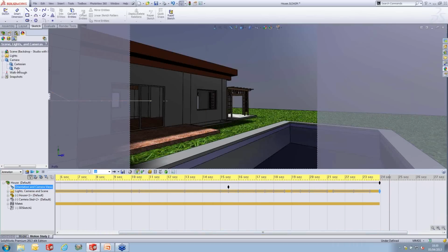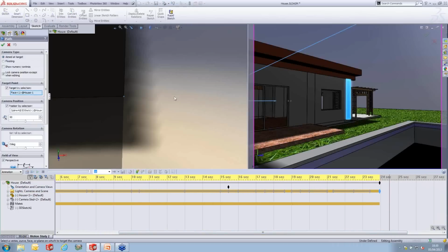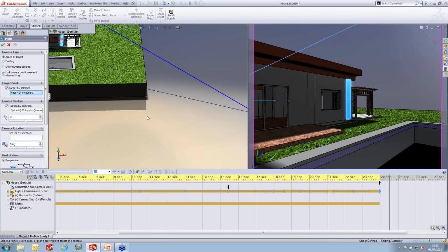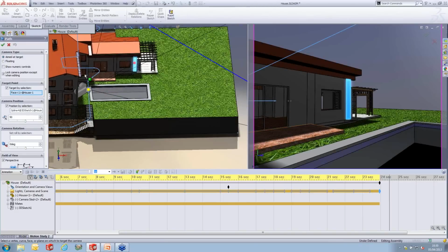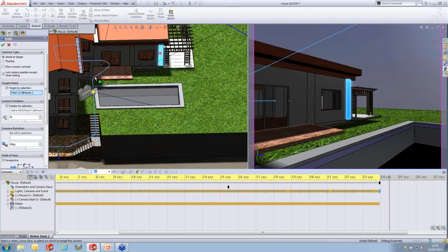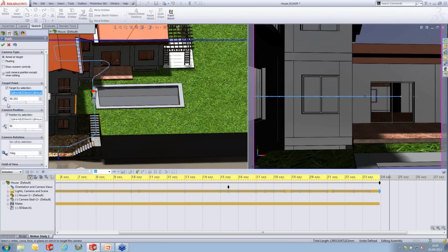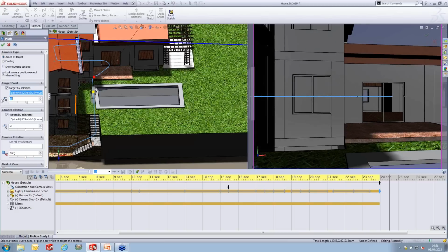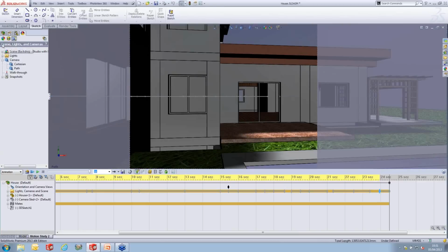Okay, move back to a sort of start point, looking this time at changing the view from the parts of the model to the spline that we created. You do just have to hover around it for a second, and then you get the percentage along the spline as a focus point as well. If I put that to 55, I'm 5% further along the spline by focusing than I am by position. That sets me up for the next part of the animation.